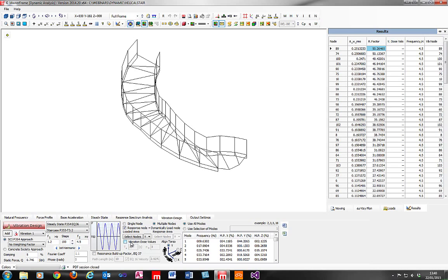And to take account of that and to modify that, the P354 gives us the choice to use something called vibration dose values. So the vibration dose value takes simply two parameters, and there's a simple equation for that in the P354. You can look it up, but it asks us for two items: TA, which is the duration that the loading takes place in.